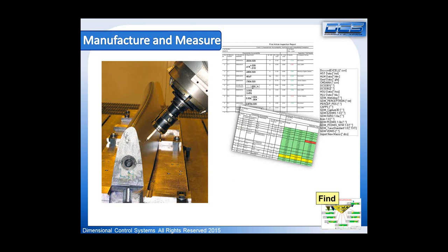So once the measurement plan has been defined and production is underway, whether it's at a single piece prototype level or at some sort of production level, the idea of being able to manufacture and then measure to the intended plan begins the first step in the ability to validate a part, but then use the information from that validation, that measurement process, to begin to develop a set of data that can be used to define or understand process capability.